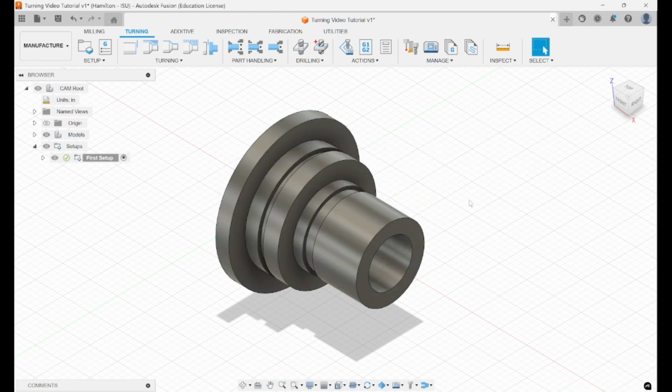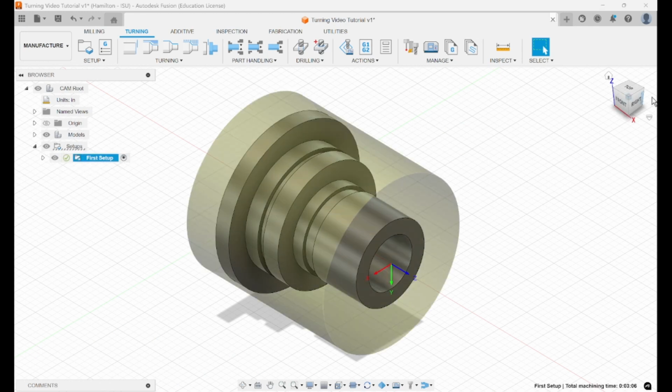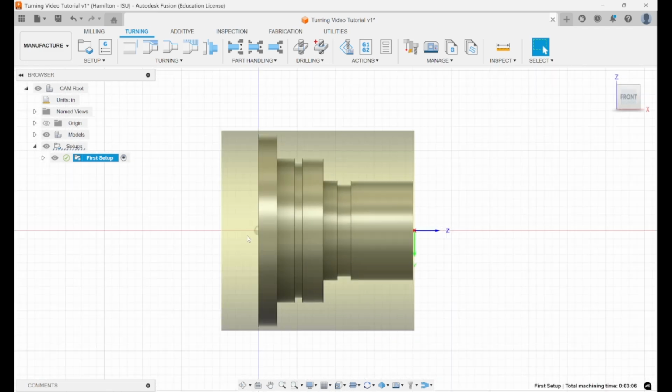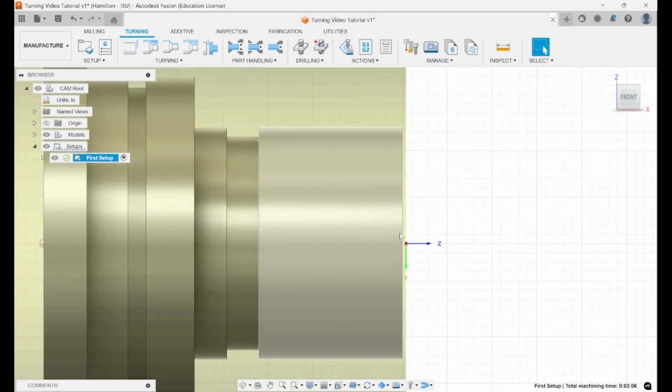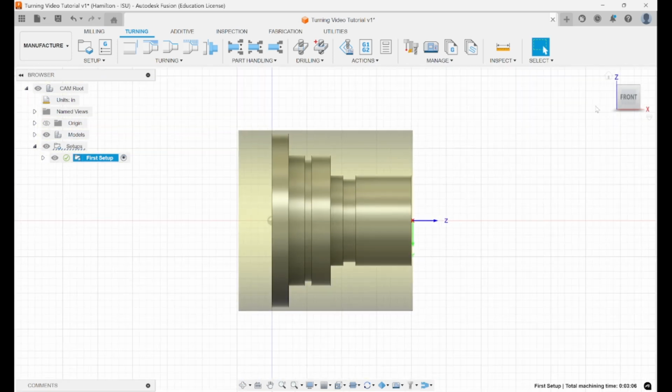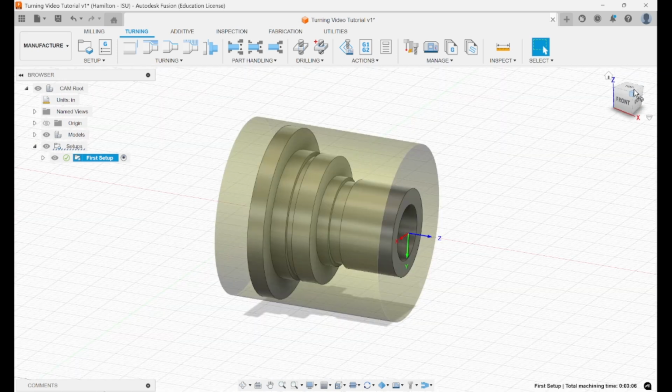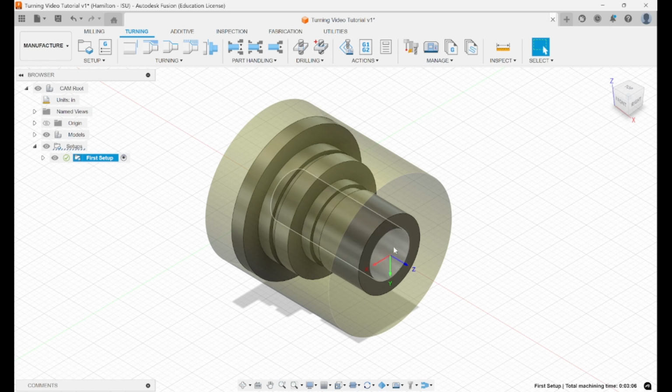So once you've closed that window, you're now free to go and explore all the different toolpaths that have been generated. You'll find them under Setups, and you can see that this setup here has been created. This setup is created with a little bit of extra stock in the back to represent what gets held onto in your machine. And has a little bit of offset of the model from the top of the stock so you get a fresh cut. It also has the origin point right in the middle of the stock.